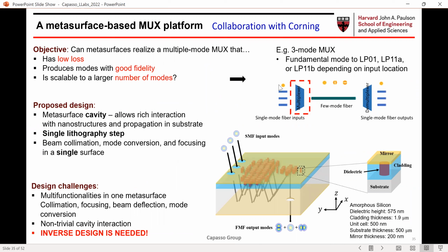Okay, so you have the input as different single mode fibers, and you want to encode the capacity of these into the 3 modes, LP01, linearly polarized modes of a few-mode fiber made by Corning in fact. And then eventually have a demultiplexer. We demonstrated the multiplexer here.